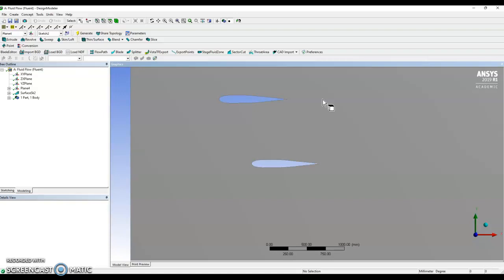You would create it with an offset of 874.268 millimeters horizontal, and then, my apologies, I mean vertical, and a horizontal offset of 438.15 millimeters. And that would give you an aerofoil with your second node placed here.